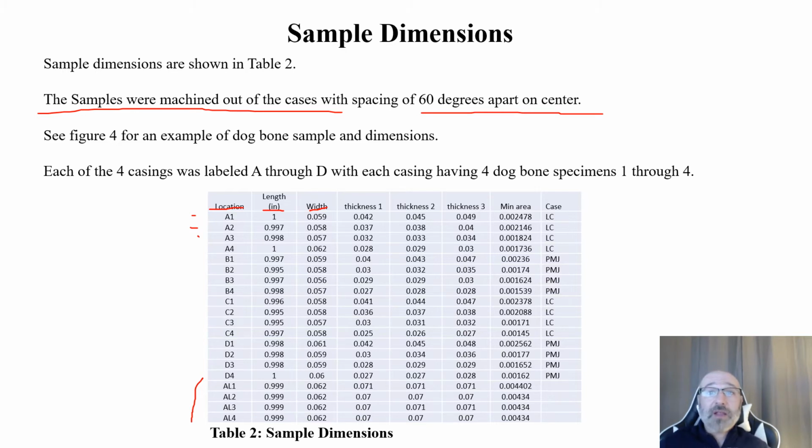The other thing, the last column over here, is which case this physically is. For NDA purposes and also for blind study purposes, we label these just A, B, C, D, and aluminum. If this was a blind study, maybe the machinist or the client knows how this test specimen name relates back to the case, so that the person running the actual tensile tests is blind to that and doesn't have any biases going in, like thinking this case is going to be better than that case or hold more, which could influence the testing results. So being blind is also something to consider when you're running these testing processes,